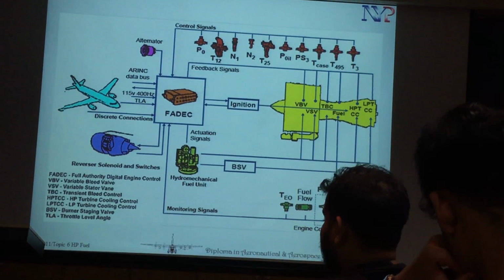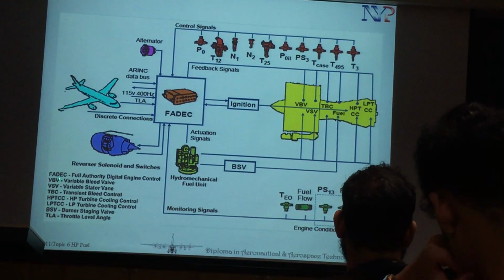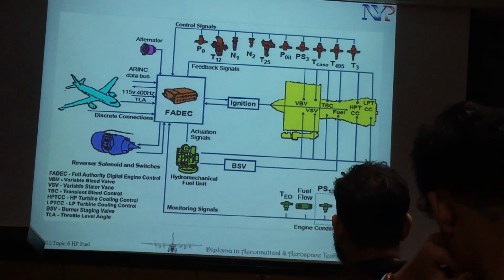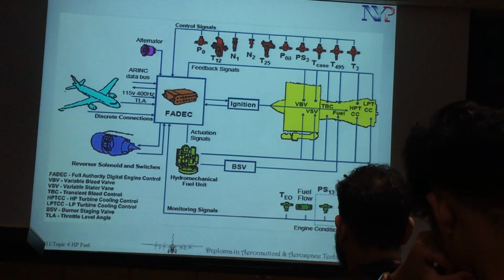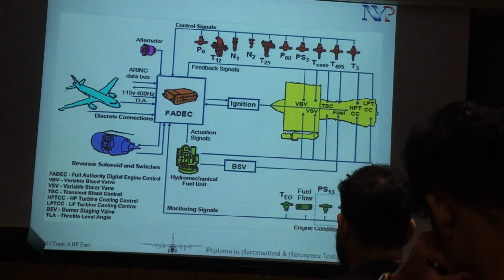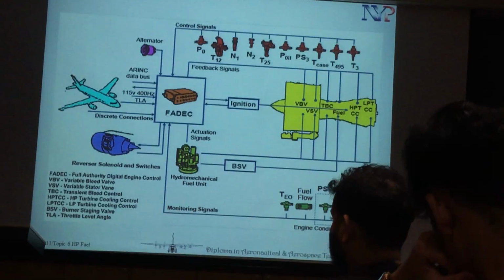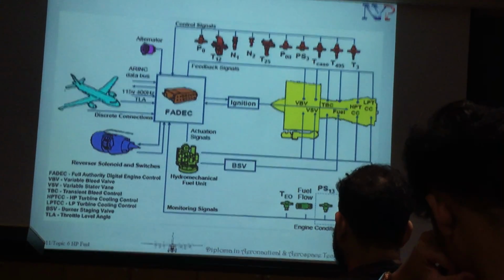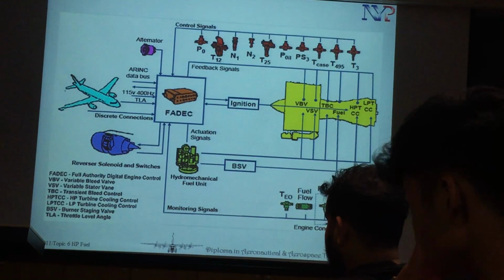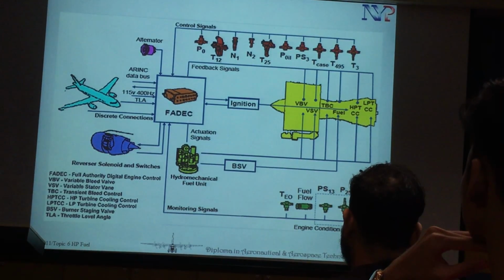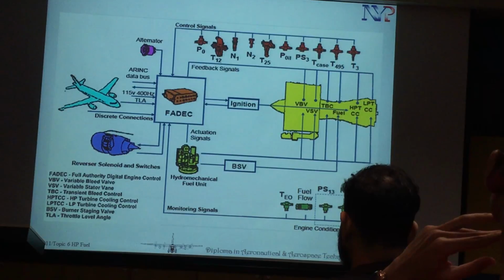Understand? So what are the advantages of FADEC? Remember, all the pilot's job is dedicated, everything dedicated to FADEC to do. Not just trimming. It takes care of all the trimming, all the overspeed, overtemp, all your scheduling done by this guy. All automatic. At the end, you're going to have a higher efficiency. Please mention that.